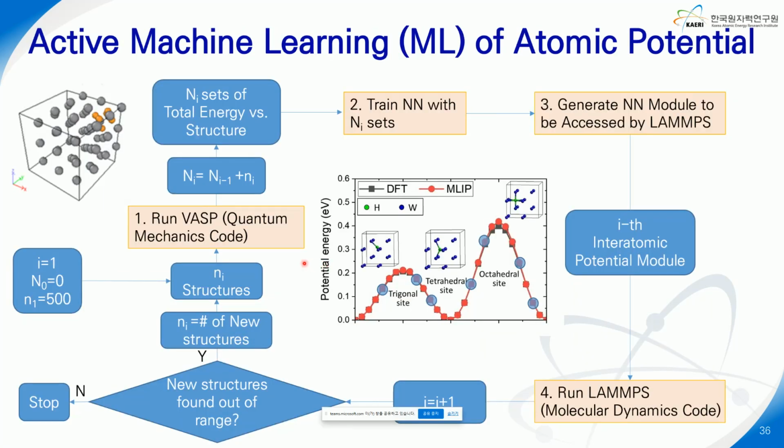Atomistic material simulation, represented typically by molecular dynamics, is used to predict material characteristics such as impurity behavior and solubility. For molecular dynamics calculation, interatomic potential, shown as this, is used in the solution of the Newton equation of motion for a group of atoms given in a lattice structure like this. The interatomic potential can be obtained by quantum mechanics calculation, which takes a lot of computing time.